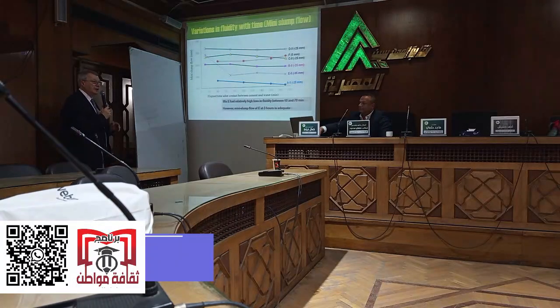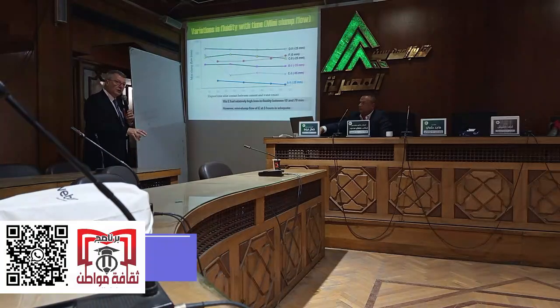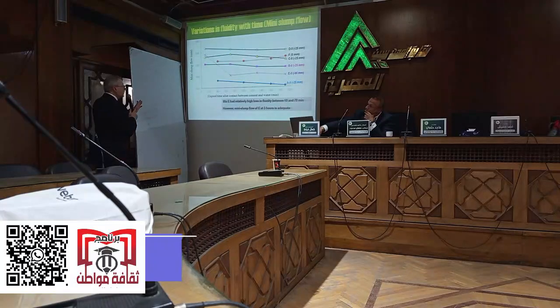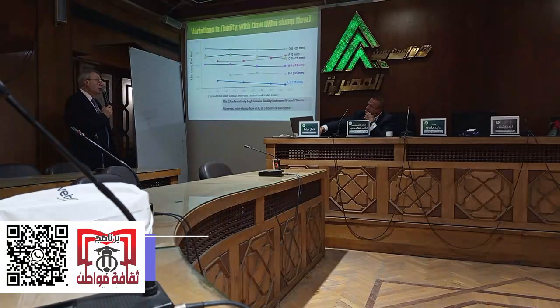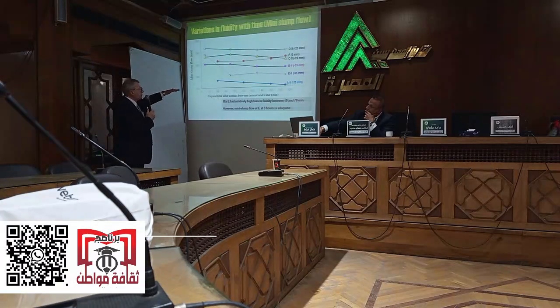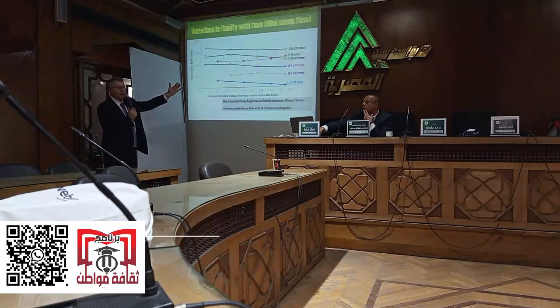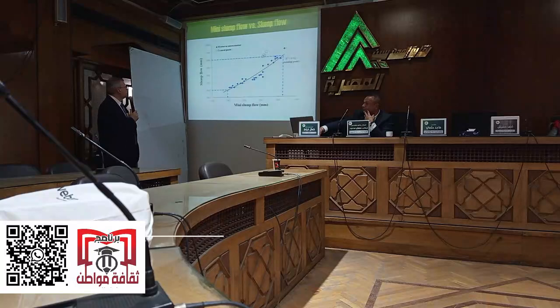We are measuring here the mini slump. Again, mini slump is a small cone. You lift it without any consolidation, you measure the diameter. We're interested in what happens initially all the way to 3 hours, 3.5 hours. And the specification was to maintain fluidity for at least 2 hours and minimize anything above 50 and at 3 hours. So you can see the materials that are produced have different fluidity, but all of them have pretty good fluidity retention.